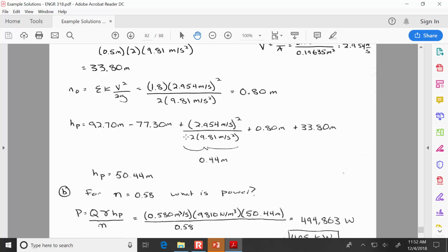Okay, the efficiency factor. Why are we dividing? It's because if it was 100% efficient, it would use less electricity than if it's 58% efficient. So if it was 100% efficient, it would need fewer watts. And since it's not 100% efficient, we know it's going to require more watts than if it was perfectly efficient. So we can't multiply by the efficiency factor, because then the number of watts required would look smaller than if it's perfectly efficient. But here we know that we're going to need more, not fewer watts, and that's the reminder of why we divide by the efficiency factor.